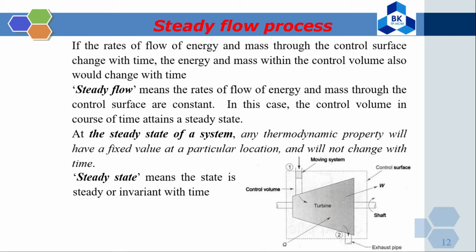And now, what are steady flow processes? If the rate of flow of energy and mass through the control surface changes with time, the energy and mass within the control volume would also change with time. What is steady flow? Steady flow means the rates of flow of energy and mass through the control surface are constant. Okay, so steady here means constant. In this case, the control volume in course of time attains a steady state.